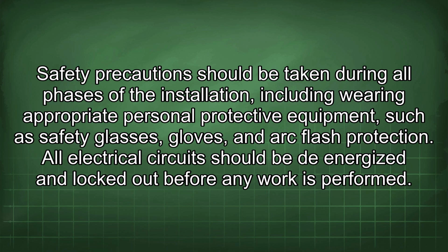Safety precautions should be taken during all phases of the installation, including wearing appropriate personal protective equipment, such as safety glasses, gloves, and arc flash protection. All electrical circuits should be de-energized and locked out before any work is performed.